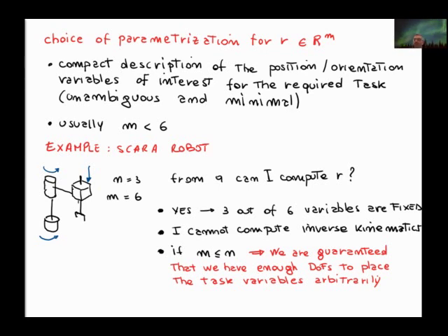Its advantage is to use it for interpolations, and the angle axis has the peculiarity to have 2 solutions in correspondence to certain orientations, and also has singularities in correspondence of an angle equal to 0 or plus minus pi. And this is because the rotation axis is undefined in that configuration.